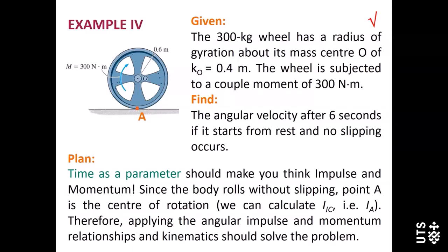And here you can see this problem involves force. Force here is a couple moment of 300 Newton meter. It involves velocity. The target is angular velocity. And time. The time here is 6 seconds. So this problem, we can solve it using principle of impulse and momentum.